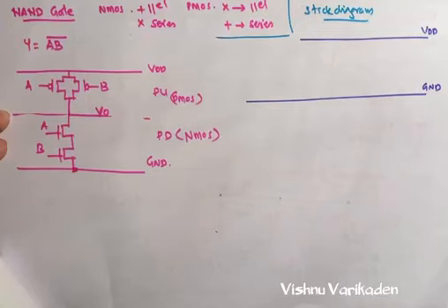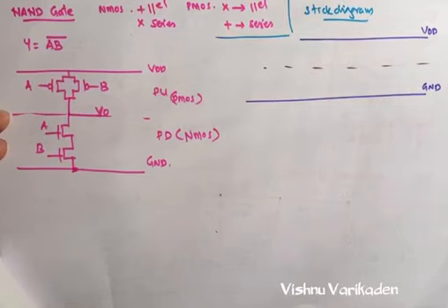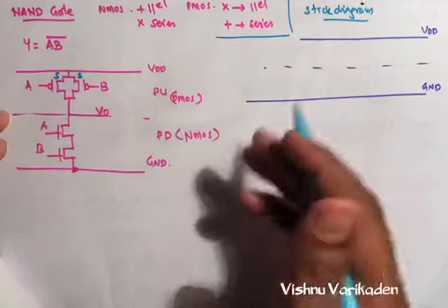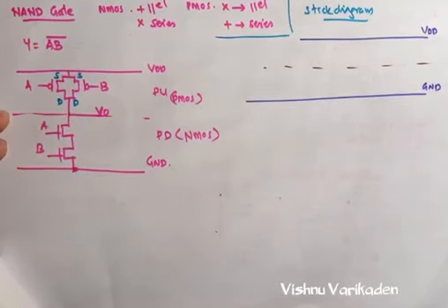So making the demarcation line. This is our demarcation line, brown dotted lines. So the next one is we can make the circuit. This is source, this is source. The two sources are connected to VDD and this one is drain.